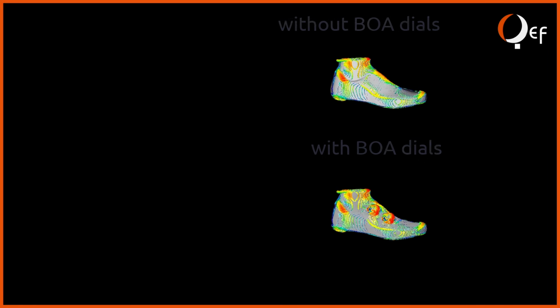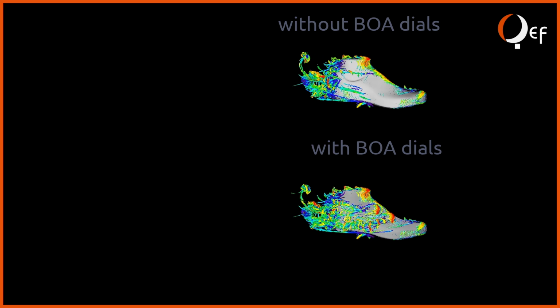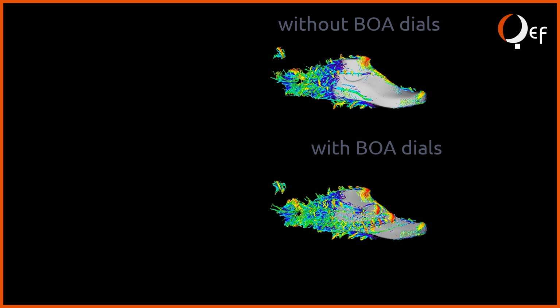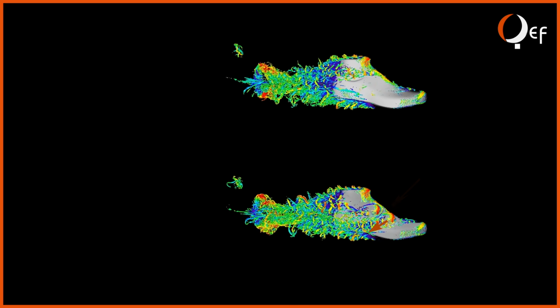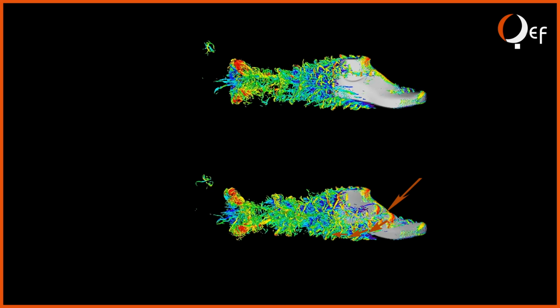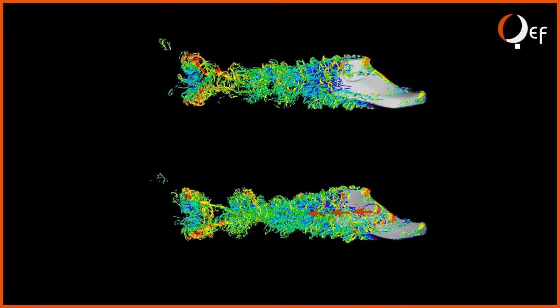In this new animation, we see the two tested shoes from a side view. We observe the same phenomena seen earlier from the top view. In particular, we highlight the turbulence generated as the airflow moves around the two BOA dials. The vortices from the front dial are deviated downwards by the air passing through the bottleneck created by the two dials. The vortices from the back dial move along the free stream direction.